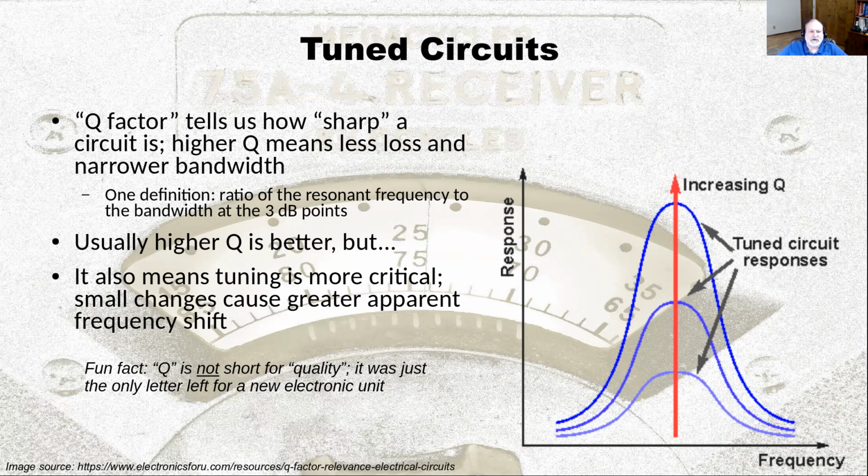So that's always a good thing, except that it also means the tuning becomes more critical because a small shift in frequency can move you off of the peak of the signal and way down the side. So you need to be careful in how you tune a high Q circuit. And just as a fun fact, turns out Q is not short for quality. It was just the only letter left for a new electronic unit when they decided to use this.